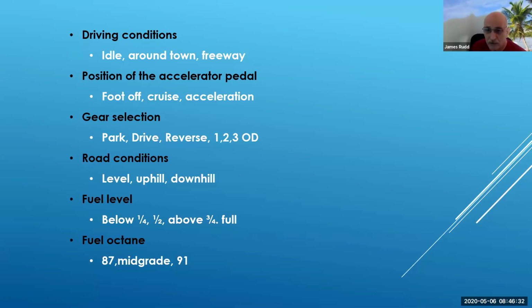Yeah, basically, when I start going uphill, I'm putting more of a load on it. And when you put more of a load on something, and sometimes you can just do it in drive with the brake applied, you can get it to hesitate. When I'm driving uphill, I'm looking for possible ignition breakdown. That's one of the first things, and that's why I like that load.